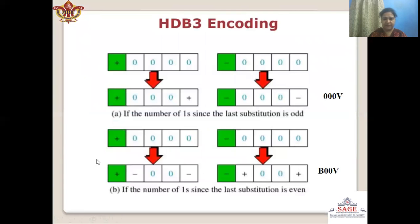Now we will see with the help of an example. Here we will consider if the number of ones since the last substitution is odd. We know that the pattern used will be 000V. Now since this is positive, 000V means violation. So since the previous was positive, the violation bit will also be positive. And if we had negative voltage, then the violation will also be negative.